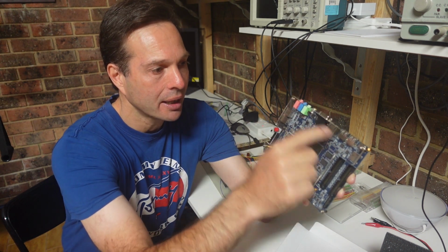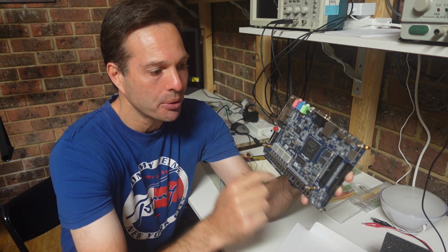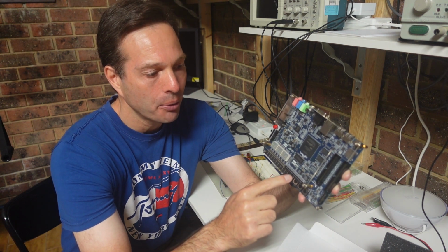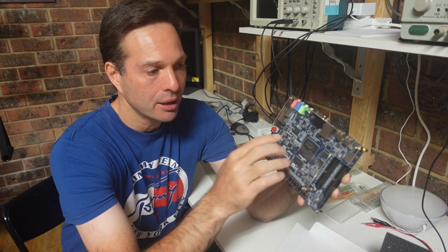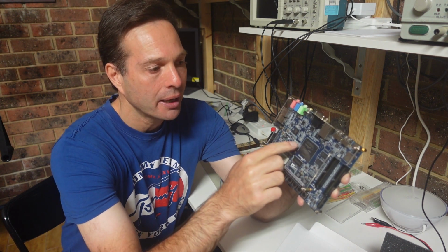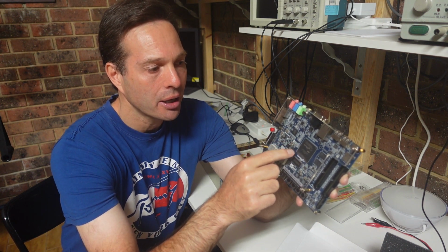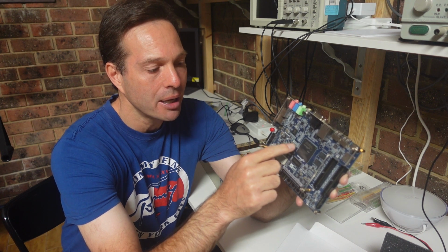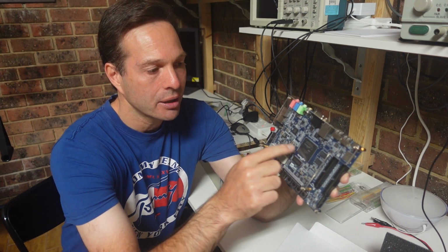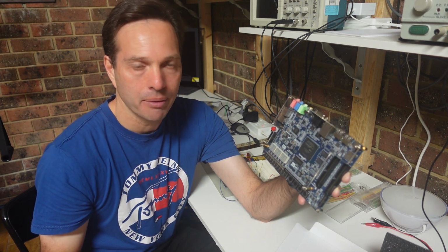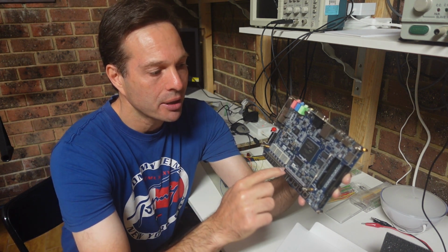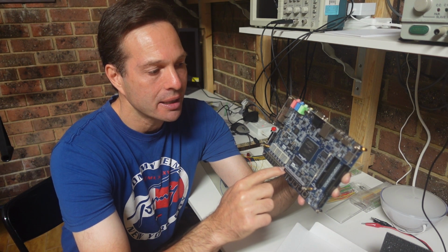And by looking at the manual that comes with this board to find out which pin this button is connected to, that's in the user manual for this board, then we can tell Quartus, well, that pin number that this switch is connected to, we want that to be the input to the circuit I just described. And similarly, we do the same with these LEDs.